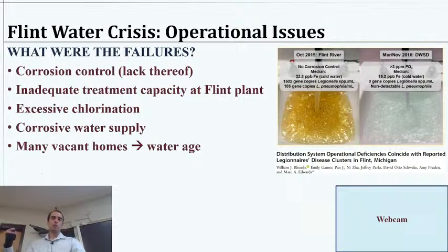They didn't add corrosion control, which is, by the way, a very simple thing to add. That's not a complex issue. It led to excessive chlorination, and on the flip side, failures to disinfect.